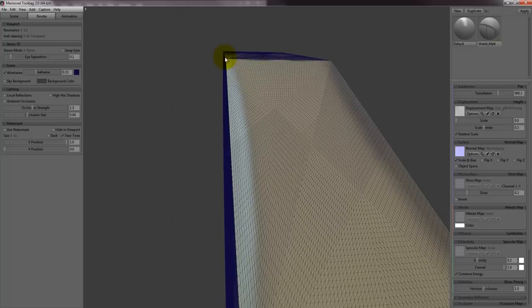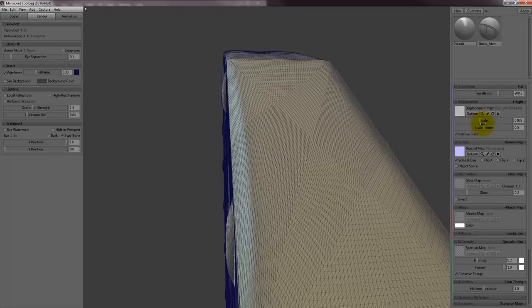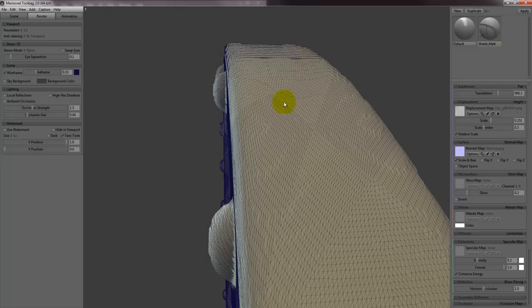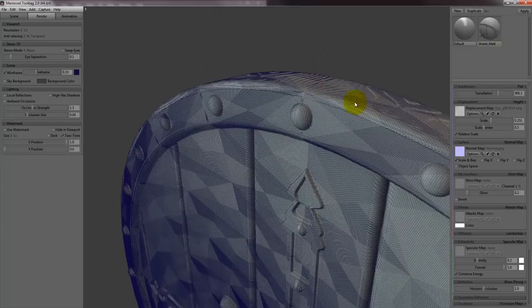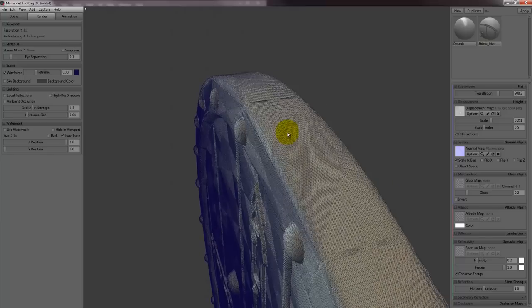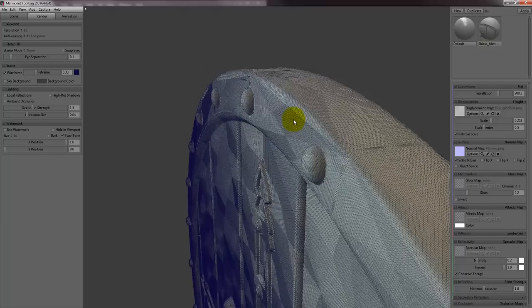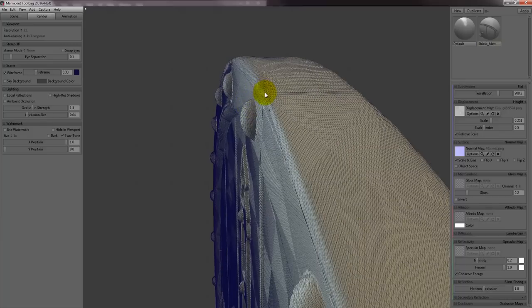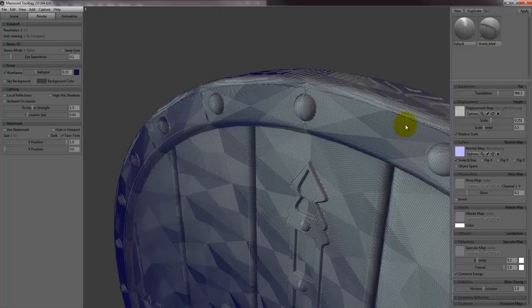But these vertices will have a vertex normal which is in roughly this direction here. Therefore, when the displacement occurs, they are not used to form the curve because of the vertex normal being in the wrong direction. So the vertices on top are used instead because their vertex normals are closer to the direction that is required to form the curve.